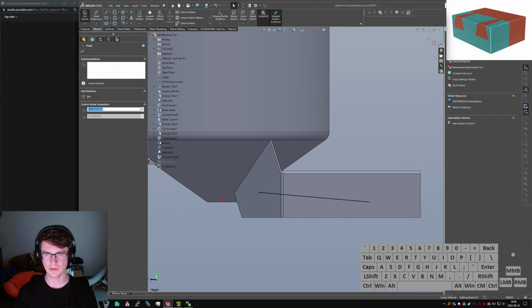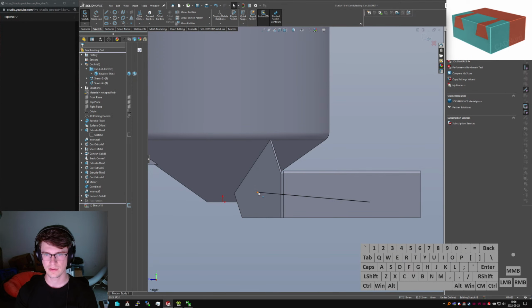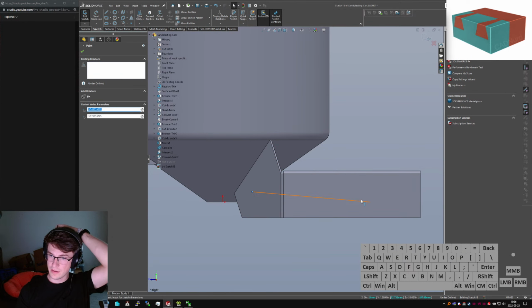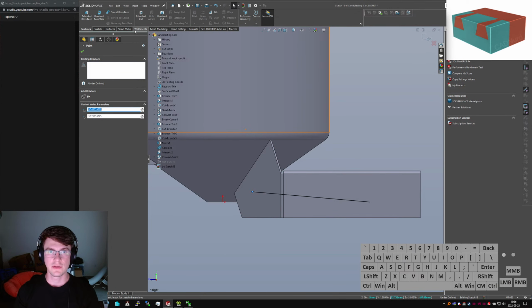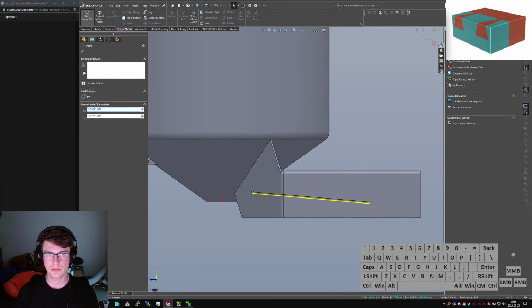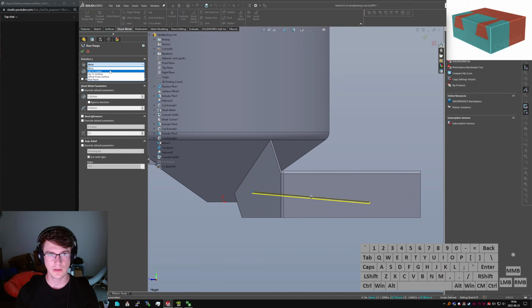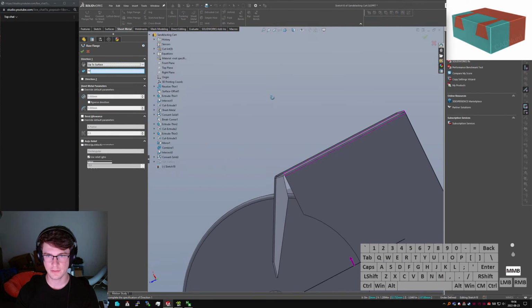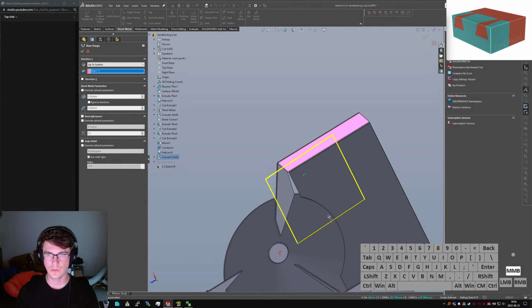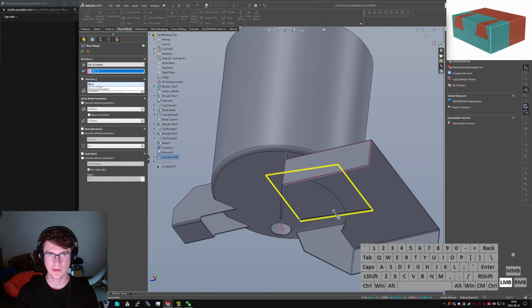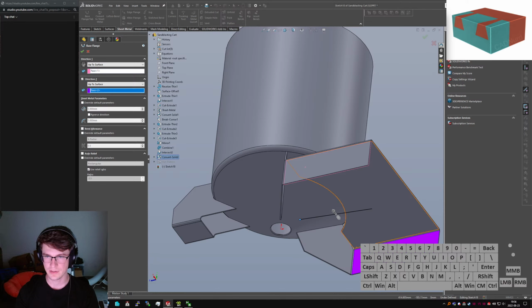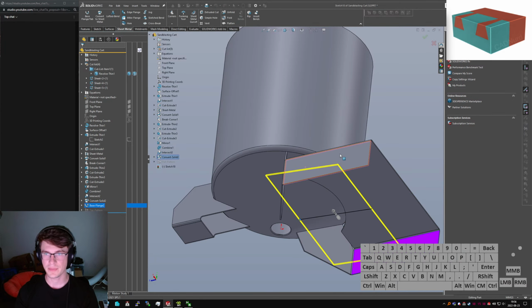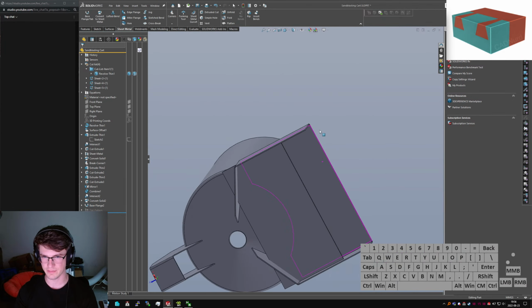Does that let me? Oh, it does let me move that. Okay, let's give that some extension then, and come out here and say features, sheet metal, base flange, up to surface. Ooh. Up to surface. There we go. Okay, here's something where you can use intersect to trim stuff off.